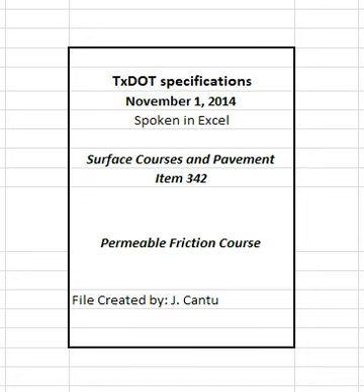2.5 Additives. Use the type and rate of additive specified when shown on the plans. Additives that facilitate mixing, compaction, or improve the quality of the mixture are allowed when approved. Provide the engineer with documentation such as the bill of lading showing the quantity of additives used in the project unless otherwise directed.